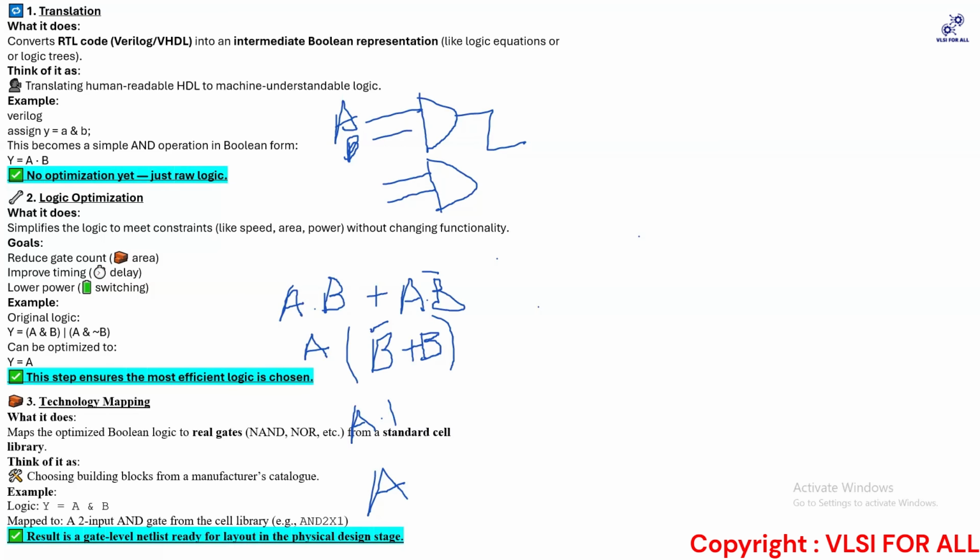But you have to understand, for example, which drive strength and which VT flavor the gate I'm using has. This is how you map, because you can't simply write AND. That is for your understanding, that this will be done using an AND gate. But which AND gate has to be specified, right? So there comes your mapping. You say that this cell has to be mapped to this library cell. This overall view of what synthesis does is called the TOM model. TOM stands for translation, optimization, and the final step is mapping.